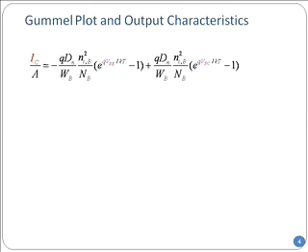Now, as soon as the V_BC is beyond a certain few kT, remember that's a negative voltage, the term that goes with the exponential of qV_BC will go to 0, because it's e to the power minus a large number. So that will go to 0, and this corresponding term will be small. So we'll drop it in the normal active region, because V_BC is reverse biased. So we drop that term, small current.